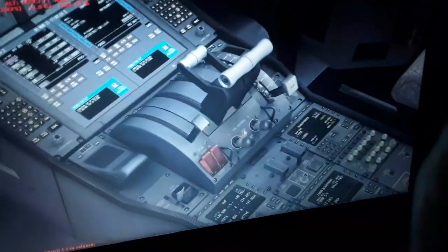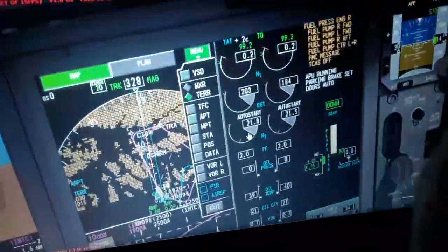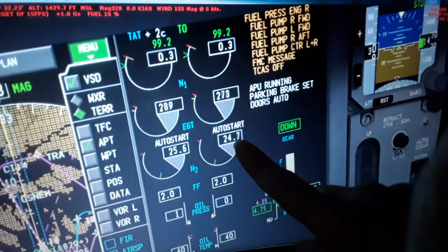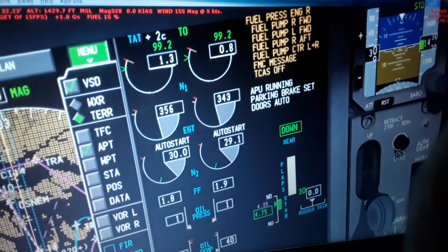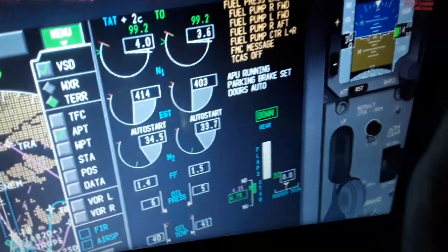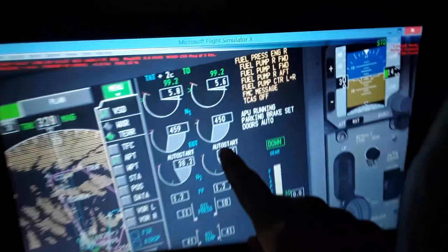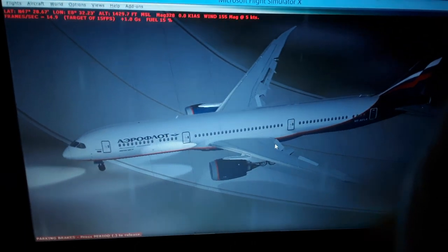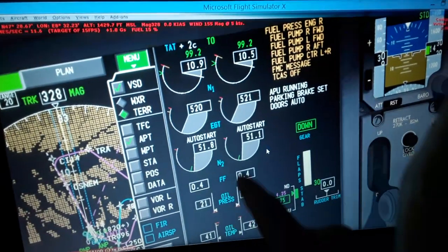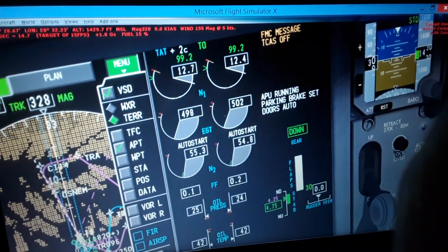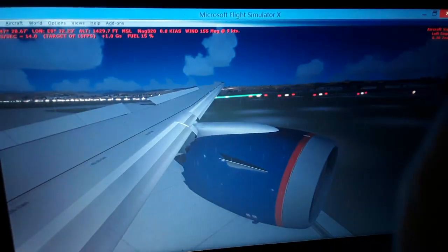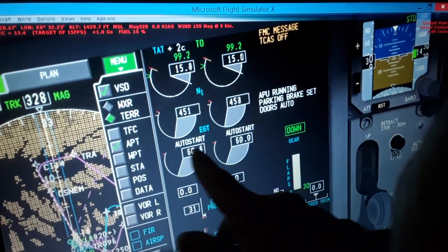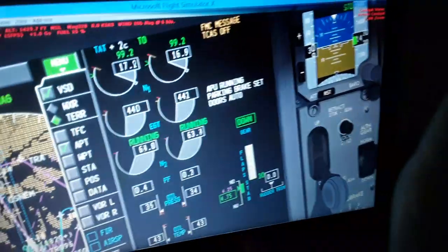So we have only pressurized air right now, so we start the fuel valves, both in the on, in the run position. And we're going to give the auto start on. So we have both left and right auto start. You can see everything now is turning on because there is fuel and pressurized air into the engine starter, both of them. Above 50%, you see also the yellow messages going off. At 62% we're going to have running engines, so we can go for takeoff.